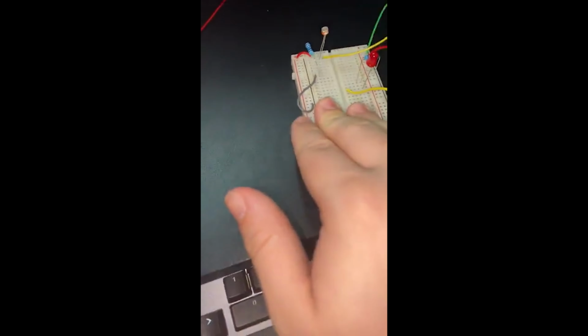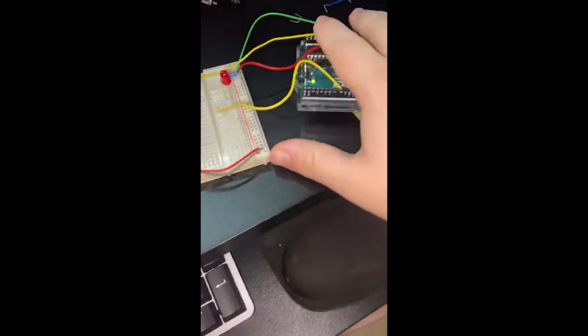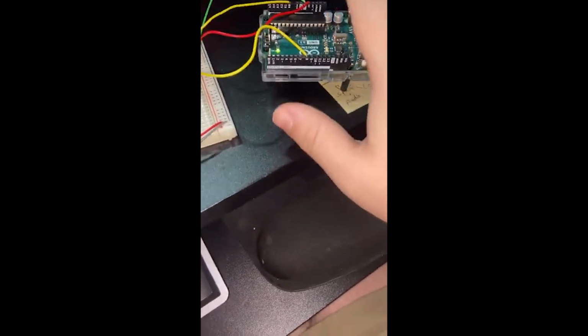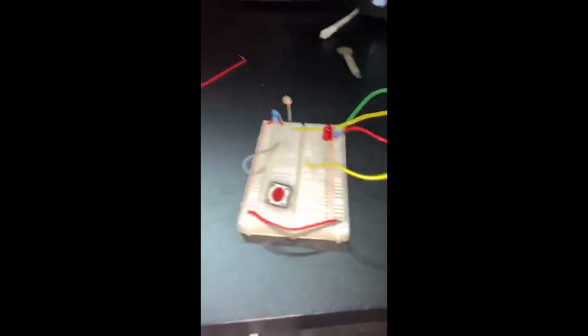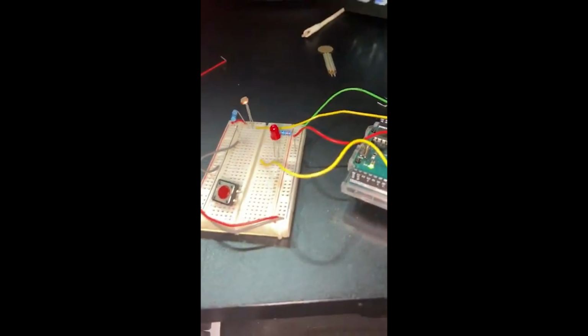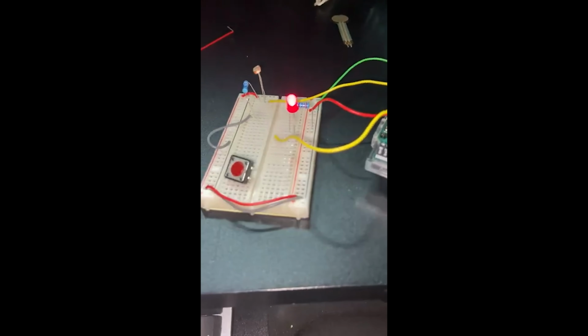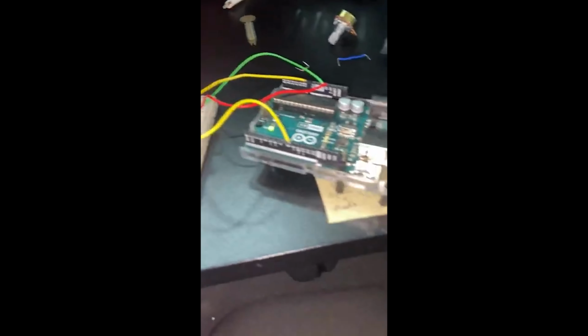So those are the two main ways we'll be working with the analog signal for now. Basically, by making a voltage divider, you can monitor what the incoming electricity is and have the Arduino respond to it. You can use whatever analog sensors you may have to have different responses. So again, it can be all kinds of different things. We've already made the Arduino do stuff with buttons. So you could utilize other aspects like maybe a joystick or again these other sensors to have your Arduino respond.